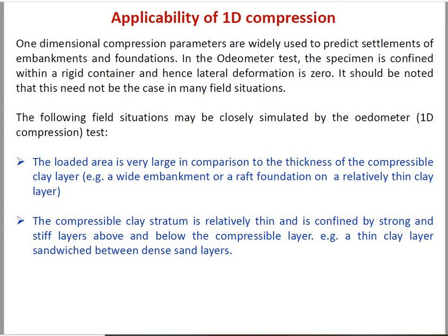But there are situations where the field condition is very well depicted by the oedometer test. If you take a very large embankment, such that the thickness of the clay layer is very small compared to the area being loaded, then that is actually 1D consolidation. Similarly, whenever a clay stratum is confined by strong stiff layers above and below, suppose a clay layer is sandwiched between two layers of dense sand, then also it will depict the laboratory oedometer condition.